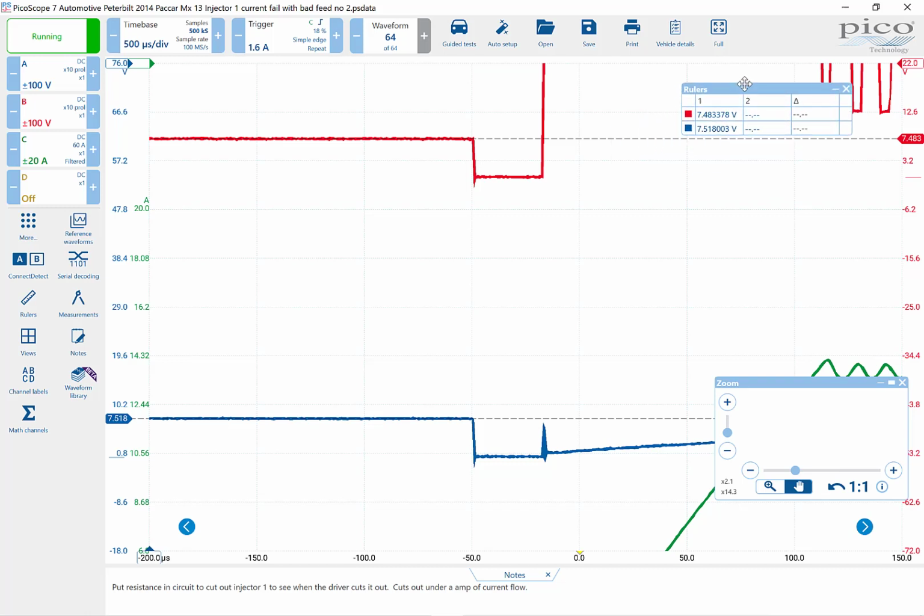So now that I've explained that, the other thing I want to show you is how these drivers are working. Here's the red, the positive, and here's the negative right here, okay? You've got 3 high side drivers per capacitor bank, and there are 2 capacitor banks. But on the ground side, each ground has its own individual driver, okay?